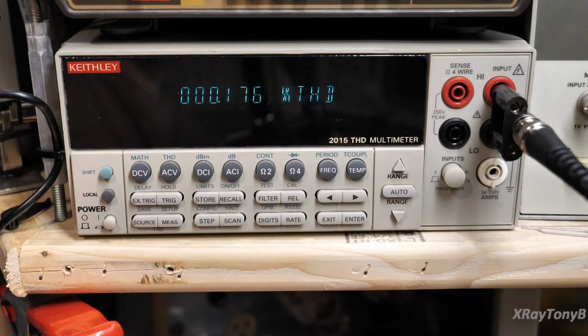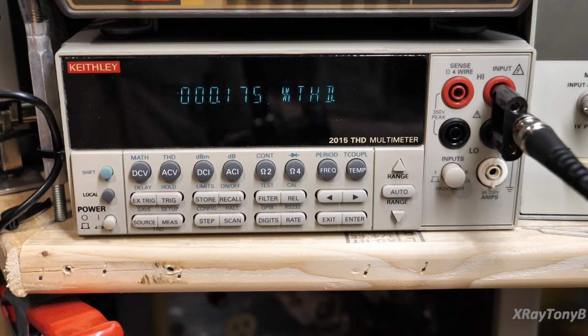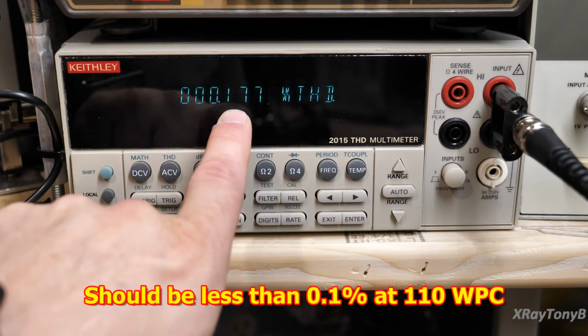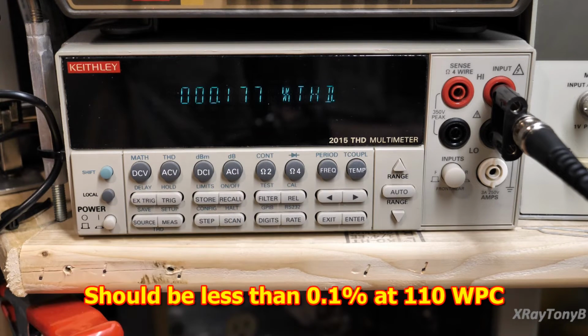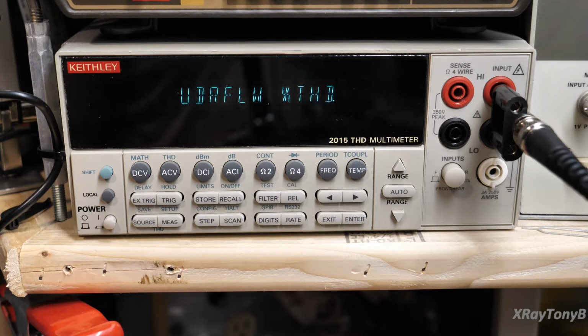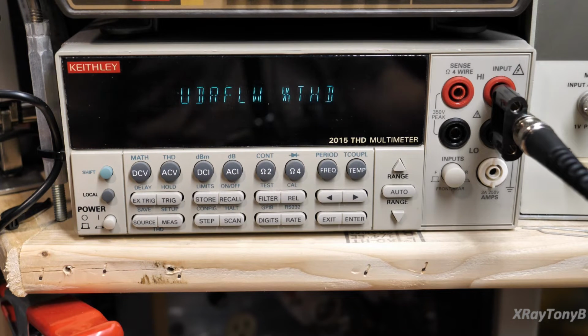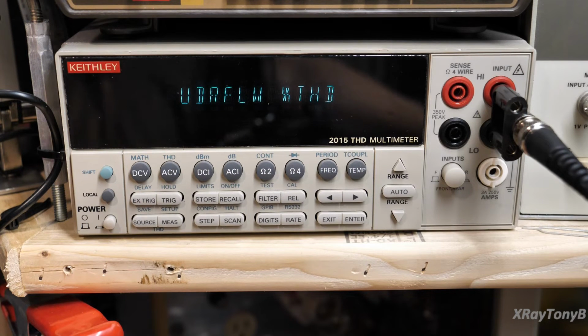And when I drive this thing almost into clipping, I'm now running this thing at over 100 watts per channel, 100 and some watts per channel. I'm only getting, again, about half of what the other channel was displaying. So obviously there are some components on the one channel that definitely can use replacing.